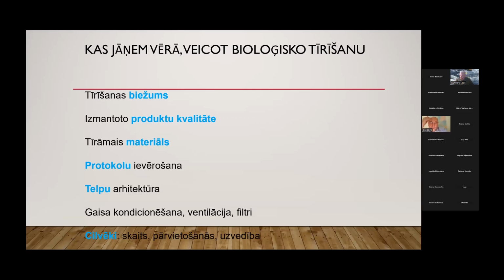I looked at the bucket and I said, don't you think there is a problem? And the person looked at me and said, no. I said, as a first thought, there is no foam, no little bubbles. Are you sure you have product? Yeah, there is product. And they opened the dosing system. There was a canister, but the canister was not connected to the system.